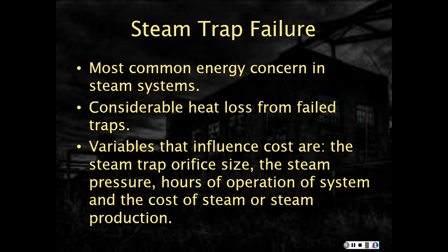Now again, because steam is a load-driven item, for all the steam that I lose through, if the boiler's large enough, it'll simply keep replacing that steam into the coil, and I'll still get some energy out for what I want to do, but I'm losing a bunch of it into the condensate line.